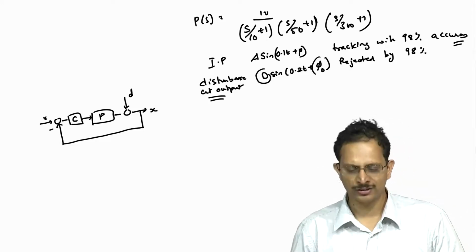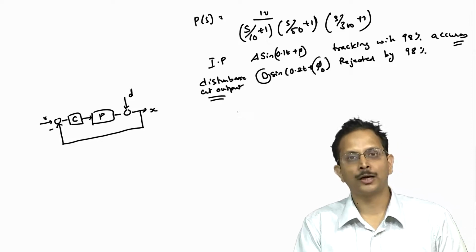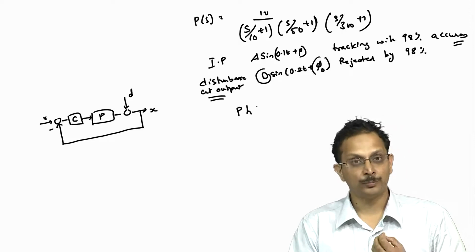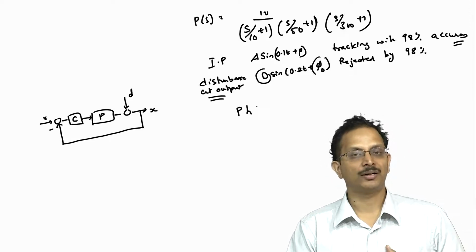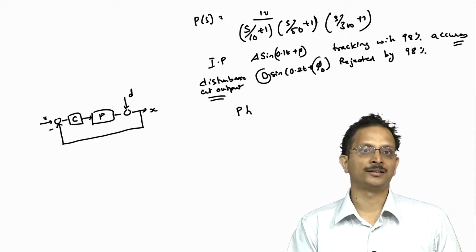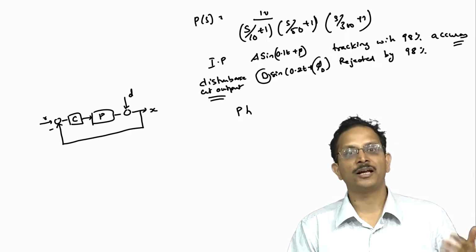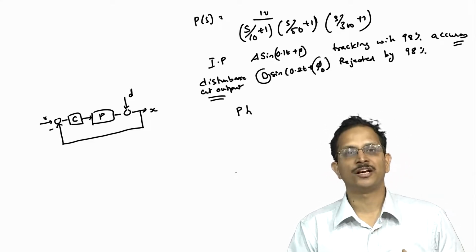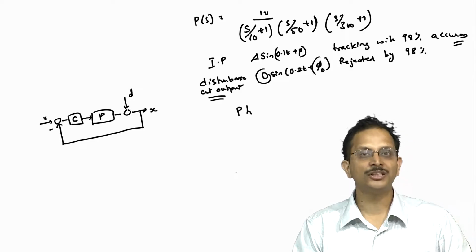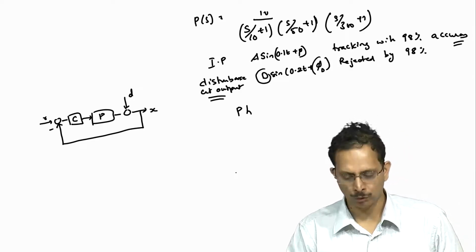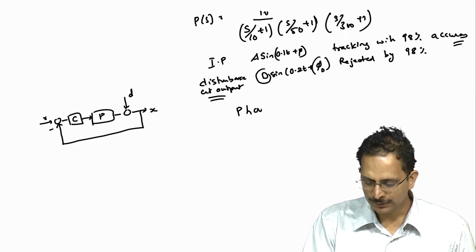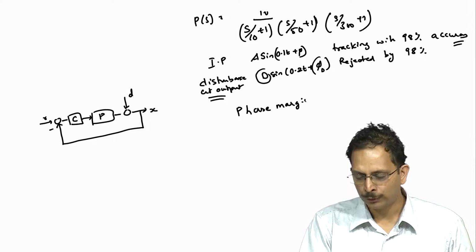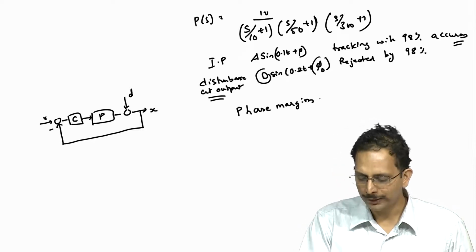In this particular case, we shall choose to design a control system whose phase margin is about 40 degrees. So, this is a specification that was not given to us, but as control engineers we know that it is important for us to achieve a certain extent of stability for our closed loop system, and therefore we have to set for ourselves a certain phase margin that allows us to achieve a certain degree of stability for our closed loop system. So, we have chosen to have a phase margin for our open loop Bode plot to be 40